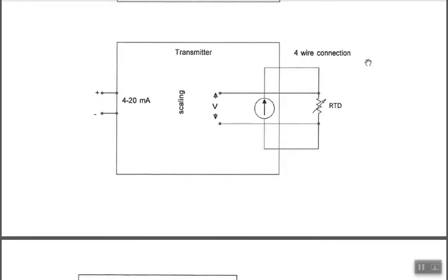Here in this diagram, you can see we solve it with a 4-wire connection to the RTD. Now the RTD is still fundamentally the same, nothing changed. It's still just its 100 ohm platinum wire from here to here. What we've done though is we've gotten our constant current source to provide current through this wire to the RTD and then return the current through this wire.